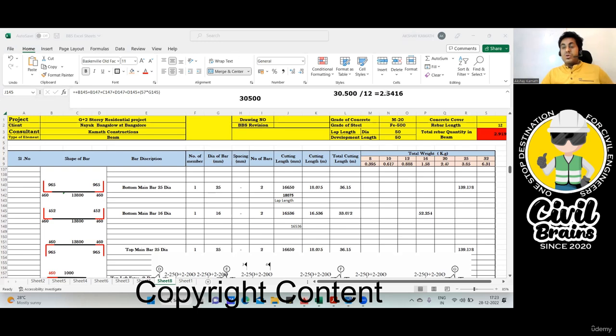Don't consider 2.5 laps; that will never come. Laps will always be in a round figure, like 2, 3, 4. So here you are concerned with only the first digit, that is 2. Whatever is coming after the decimal point, you just neglect it. So in that case, you'll do 2 lap length, that is 2 into 57 into diameter of the bar. Got it? Fine.